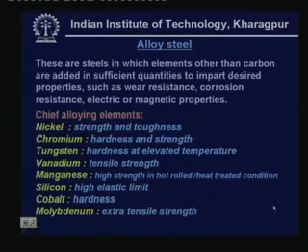These are the steels in which elements other than carbon are added in sufficient quantities to impart desired properties such as wear resistance, corrosion resistance, electric or magnetic properties, etc. As I was just telling you, these alloy steels are used for special purposes, depending upon the type of use and the environment.